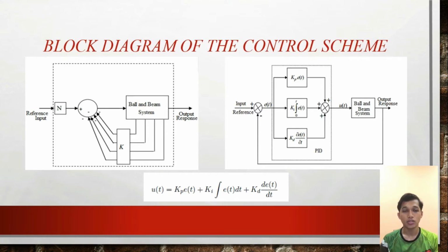We can also see the equation where u(t) is the control signal, KD, KI and KP are the derivative, integral and proportional gains, and e(t) is the error owing to the difference between the response signal and the desired signal respectively. Proportional gain improves reaction speed, but a faster response introduces a steady state inaccuracy, so we set the PID to obtain optimum response. The integral gain is a good solution for the steady state error. Overshoot is another undesirable response pattern that can be corrected with the derivative gain.